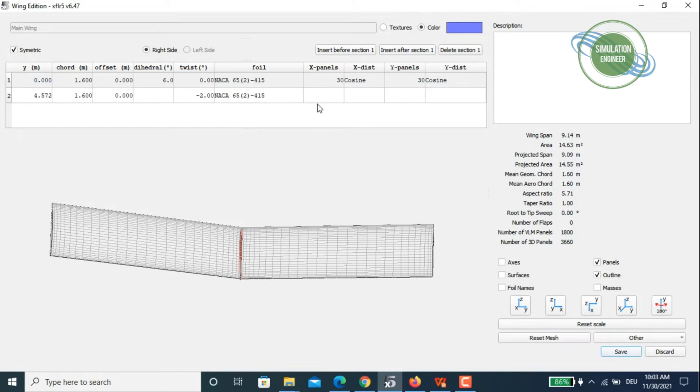It is recommended to use the number of panels, spanwise or in the streamwise direction, chordwise, from 20 to 30 panels, which is a good approximate compromise, I would say, based on personal experience. I'm not claiming this is the best number of panels, but you can stick with it and try with it. If you get some better strategy for this, just let me know also.